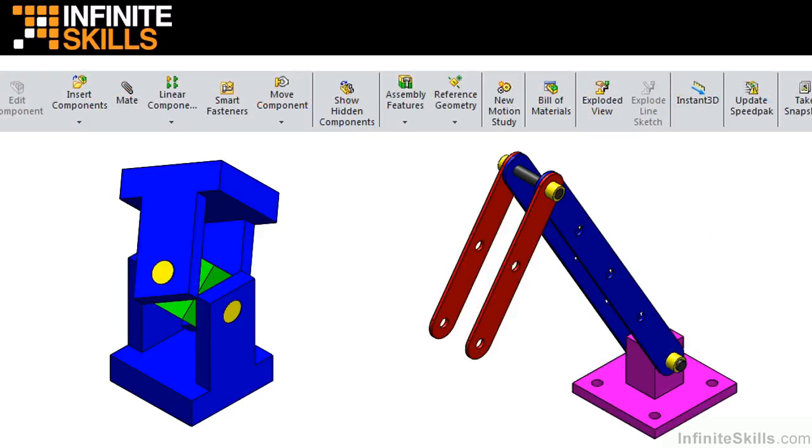After we conclude the discussion on features and part creation, we will move on to assemblies. In an assembly, we apply the similar relations that we apply when we create sketches. However, we call these relations mates. Just as sketch relations define conditions such as tangency, parallelism, and concentricity with respect to sketch geometry, assembly mates define equivalent relations with respect to the individual parts or components, allowing the easy construction of assemblies. In the assembly lessons, we will cover all of the standard mates along with a few intermediate assembly techniques.